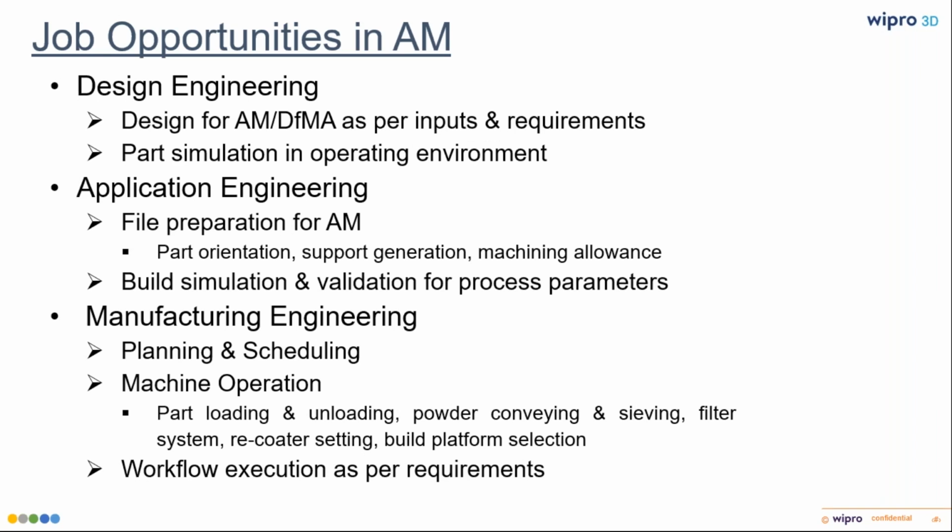And once this part has been realized, you need to carry out a simulation in the operating environment. Even though you have the part, it's not as simple as putting in the CAD geometry and ending up with the as-required geometry. You need to simulate this design for checking delamination and warpage, because as I mentioned, if you are working with selective laser melting or direct metal laser sintering, we are working with a lot of residual stresses, and thermal management can become difficult. So before putting it in the machine, we would want to simulate the part build in the operating environment based on whatever parameters we have set for the build.